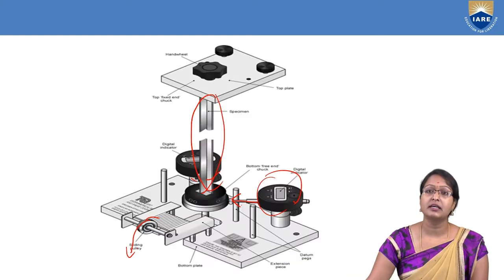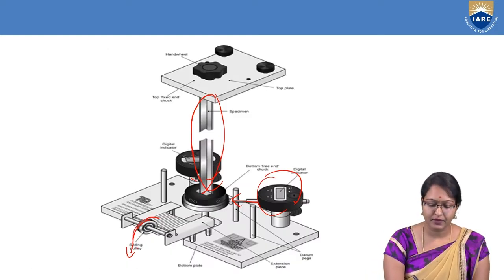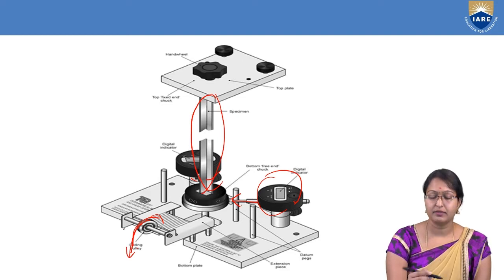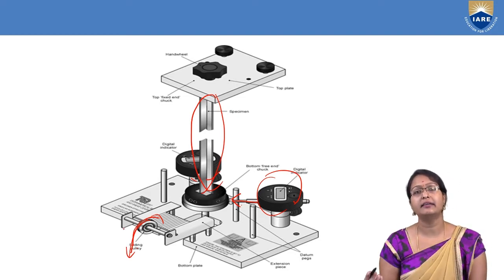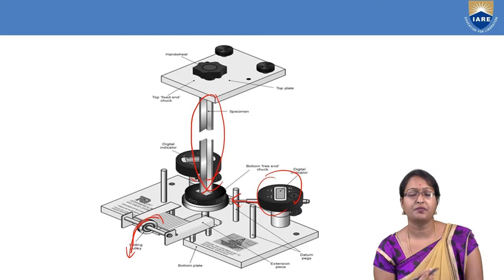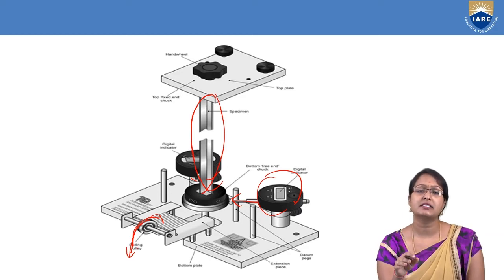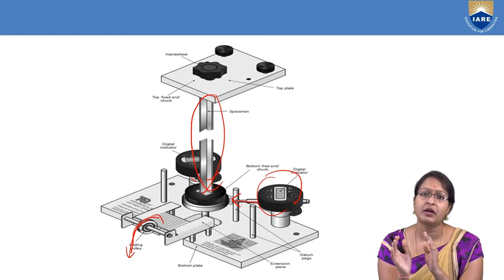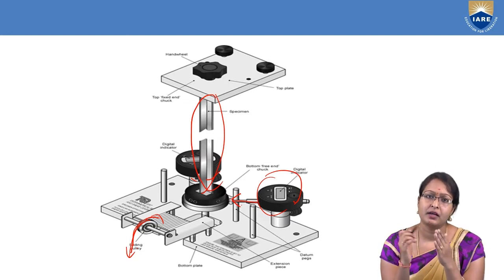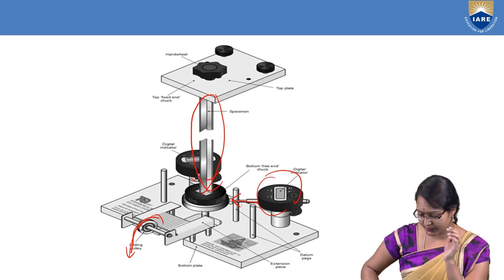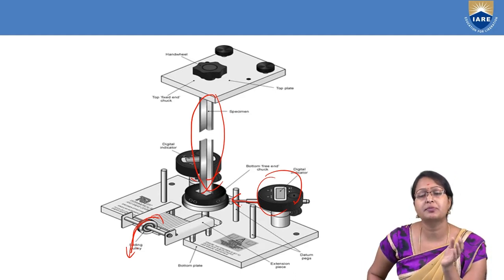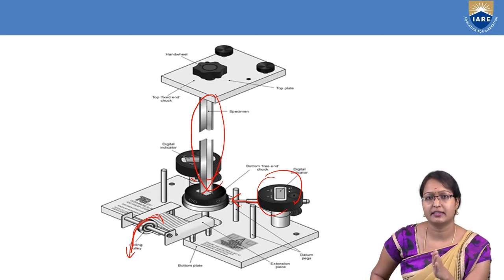Here we add the weights as per the requirement from the left end to the right end, and we get the deflections where twisting and bending occur. We plot these, and at the particular point where we get no twisting, only pure bending, we have got the shear center.